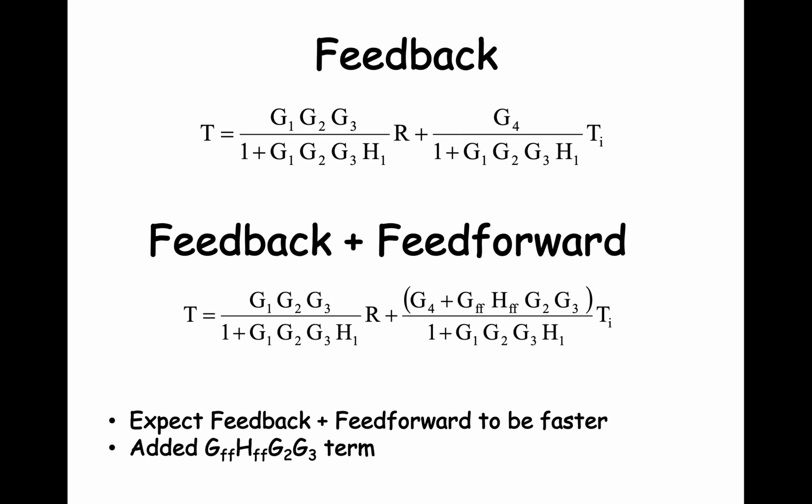The one with feedback control only is on the top, and the one with feedback plus feed-forward is on the bottom. Feed-forward adds the term GFF times HFF times G2 times G3 to the regulator term of the overall transfer function. Feed-forward tuning is beyond what we can cover in this course.